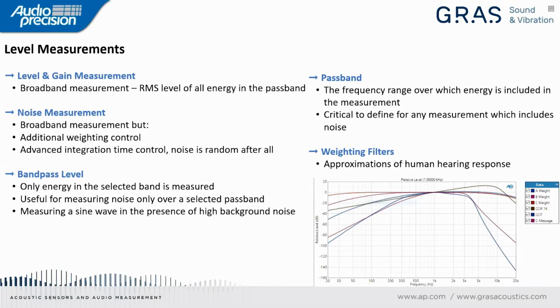In APX, the equivalent is our level and gain measurement. And we describe this as a broadband measurement. So it measures all the energy in the currently defined instrument passband. It measures your fundamental, any noise, any distortion, all of that gets added together, and you just get one result. If that's what we want, that's great. But sometimes we're looking for peculiar things.